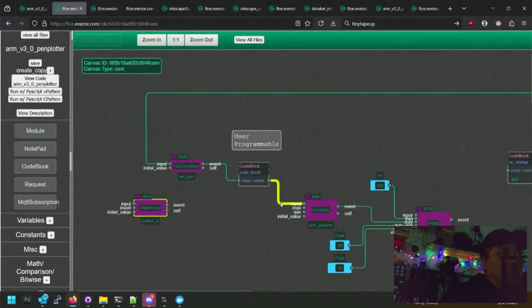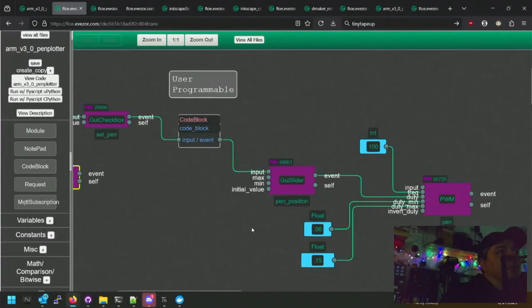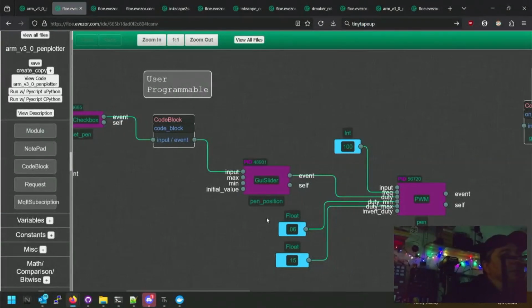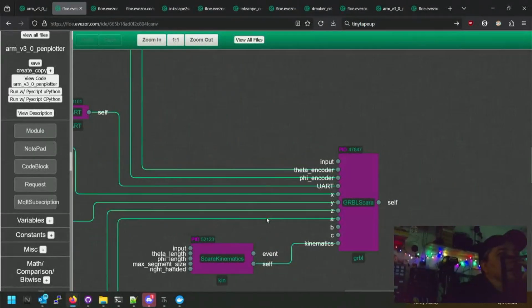So in this, is the servo controlled by G code, or is it at a higher level in here? It's at the higher level up here. Okay. So the actual pin that is running the PWM signal is the host, running MicroPython. So you're not using G code for Z moves, that's interesting. Yeah, I mean, effectively it could be. So where is the verbal interface block? That is this guy here.